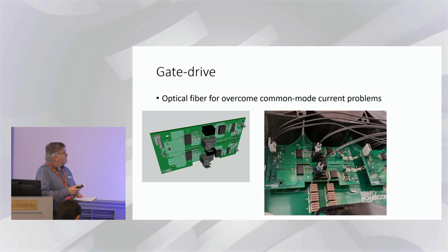And we have optical interface, 1 for high side, 1 for low side. And the best driver we could find on the market with lowest impedance we used here. But this is not the final solution. We don't have any overcurrent protection. We don't have any temperature measurement. So this is just more or less a prototype to continue the power test.